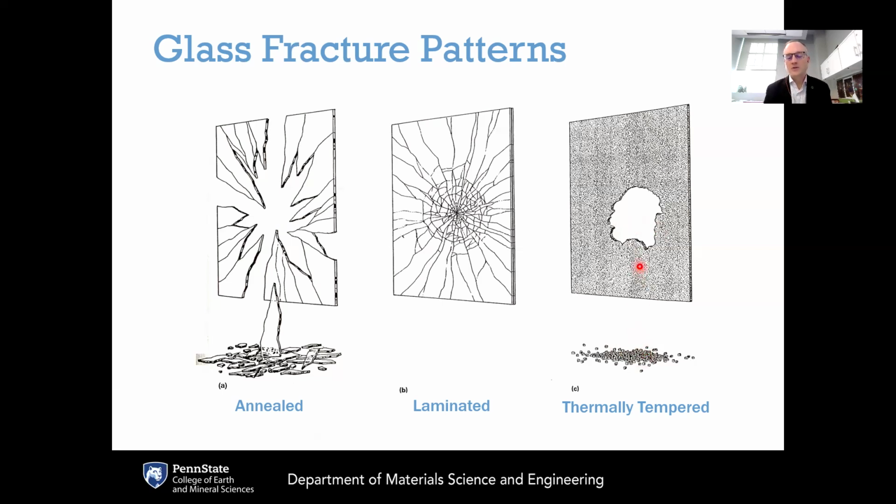This is what's called frangibility. Frangibility occurs when a glass breaks into very small pieces as a result of branching of the cracks due to the release of tensile energy from the interior of the glass.